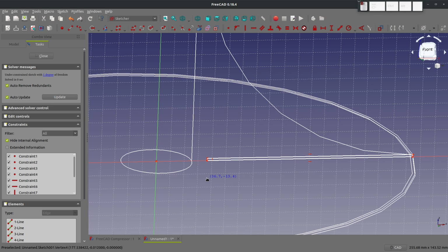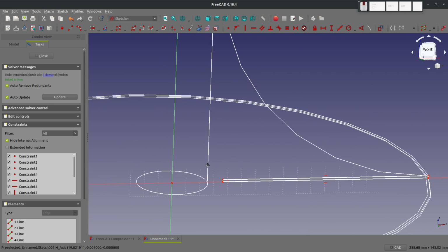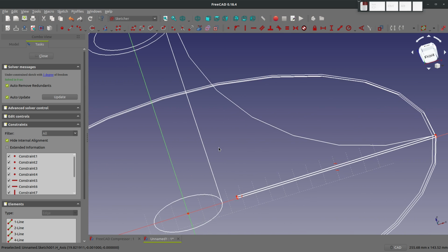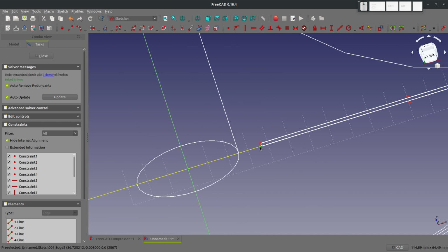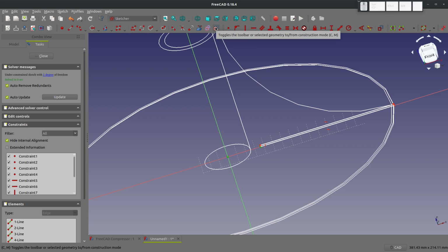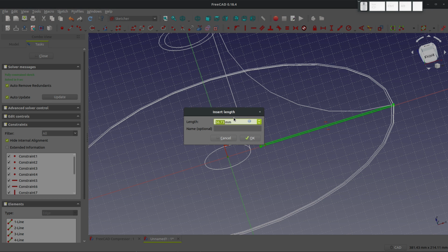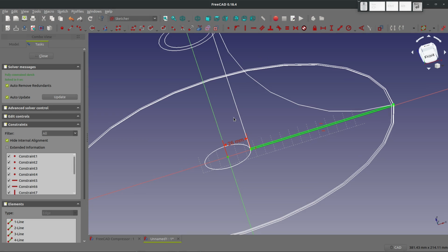And let's see, our inner axis part was 25.4. So to avoid a possible zero thickness error, maybe if we have no zero thickness, it'll work. I don't know. Let's go with Shift H and maybe 26 millimeters, right?